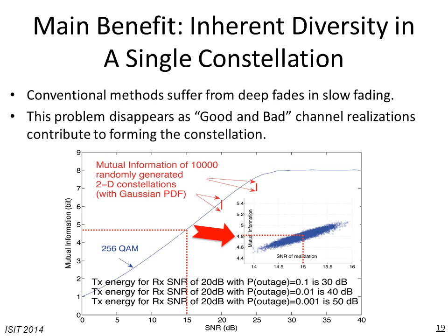For a probability of outage of 10 to the power of minus 3, we need 30 dB. While for the case of media-based, for 10,000 realizations, you see that if we have a provision of about 1 dB, none of those 10,000 realizations get into the situation where the mutual information is less than 4.8, which is what we expect to have.